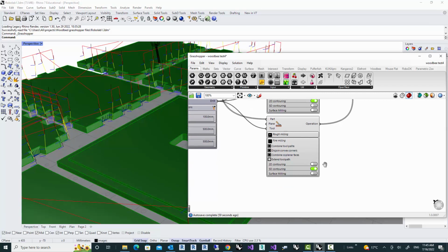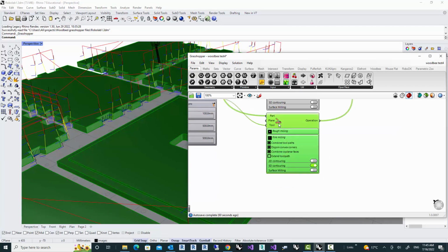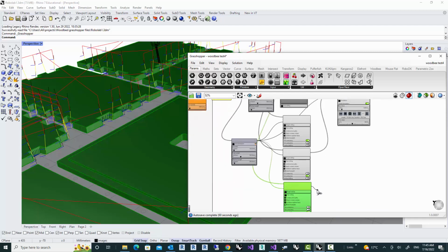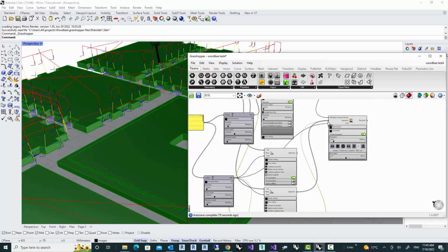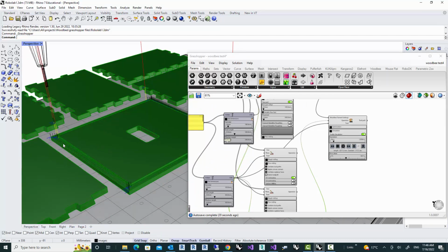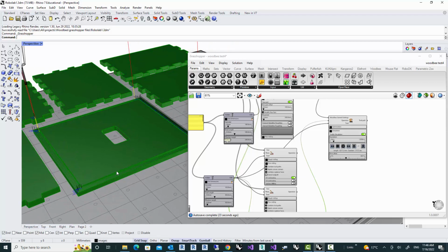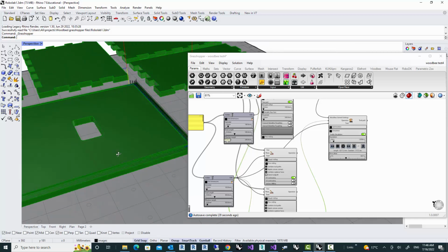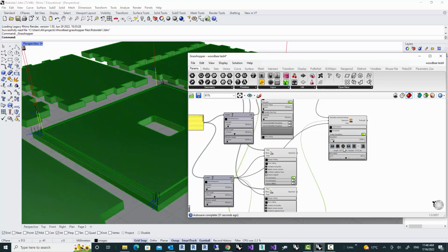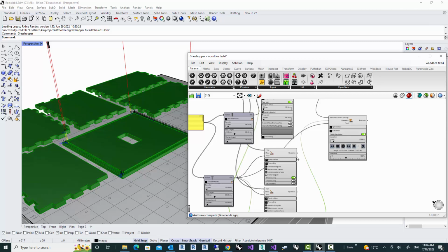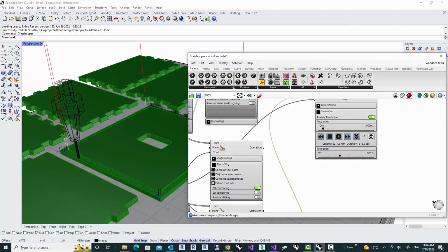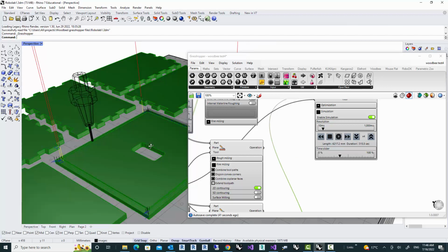So I'm just going to copy this again, and we're going to choose surface milling instead of 5D contouring, and we connect that to our simulator. So as you can see, this component has automatically detected where it's possible to mill using the tip of the drill, and it has created the toolpath. And we're going to look at it once. So it just moves perpendicular to that surface and removes the material.